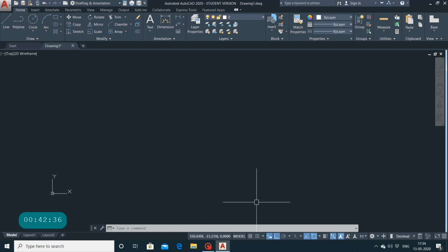Control plus C to copy object, Control plus V to paste the copied object, Control plus Shift plus V to paste the copied object as a block. You can use this keyboard shortcut. The block thus created will have a random set of characters as its name. Control plus Z, undo last operation. Control plus Y to redo the last undo action. If you have just undone the last action, then immediately if you use Control plus Y, then it will redo. You also have the redo here.